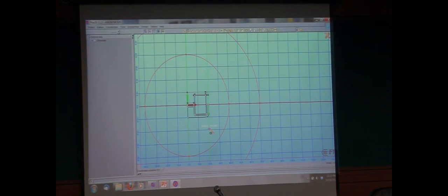So as a reminder, this is a true open boundary problem. That means that everything past this border is computed as if I was going to infinity. It is doing a conformal mapping of the outer space within this band right there. By the way, a little information, you can see the program says I cannot change those lines because those lines are actually a very special type of line. They were associated to the infinity box.